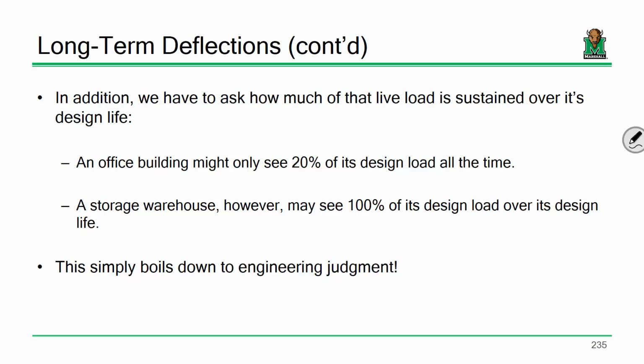Do you think 80 pounds per square foot is going to be on that floor system all day, every day? Not necessarily. Take the people in this room: in about 10 minutes, this class is going to be over and you all are going to be out of here, so this load on this floor system is not sustained. In an office building, you might say 80 pounds per square foot, but really only 20% of that is going to be there all the time.